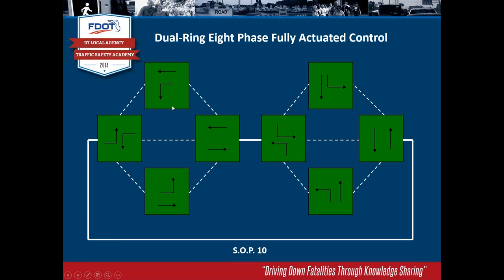And again, let me emphasize, this shows all the possibilities of what you have in the situations here in the middle on both sides of the barrier, which, again, the barrier would be in here. This is what's called typically an overlap phase. It's an or condition. You'll either have, from the situation where the lefts are together, but before we get to the throughs being together, you may have one left heavier than the other, so you may see this, or you might see that one, or you might just go straight from lefts to throughs at the same time, especially if the lefts are both really heavily demanded and they both max out.